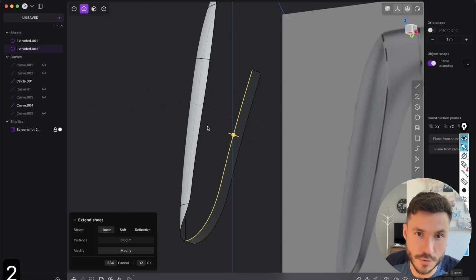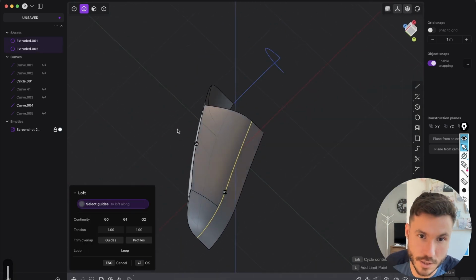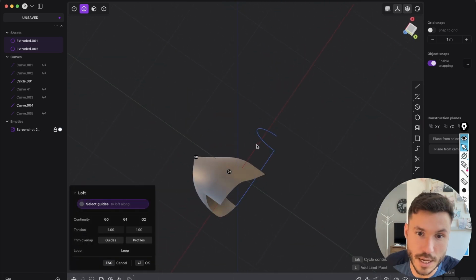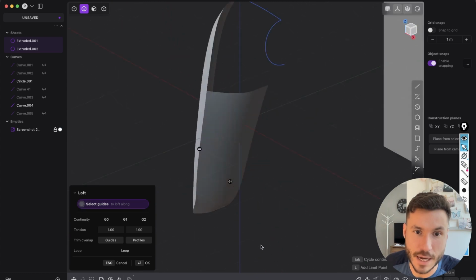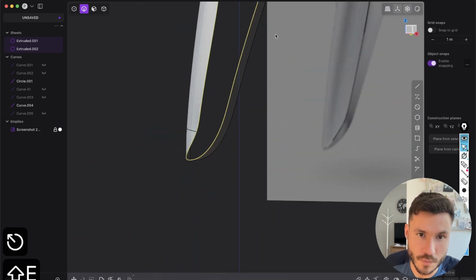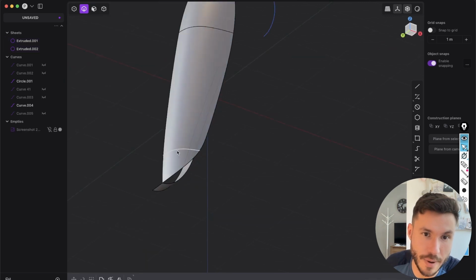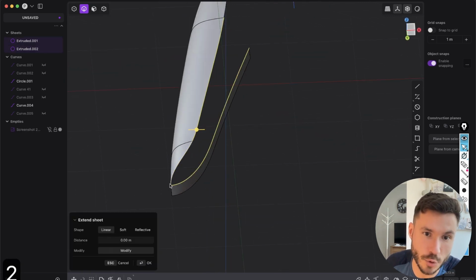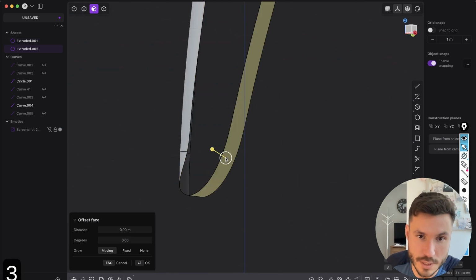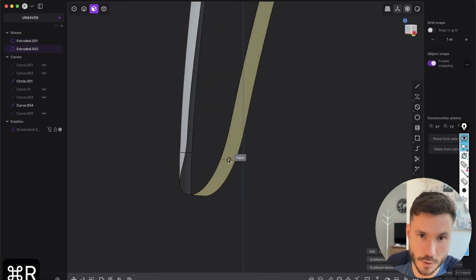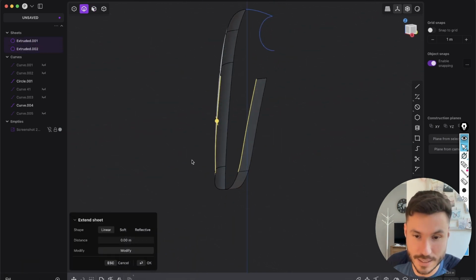And now we can try to loft that. Loft, but give it here G0. And this result is okay. But I want a little bit more control. Because if you remember, so let me hide this image here. If you remember here, we didn't want to loft that when they are meeting, right? So we broke up this edge. So we do the same here, select this face and Ctrl R or isoparam and just add an extra edge, because now we have exactly the same, bam.